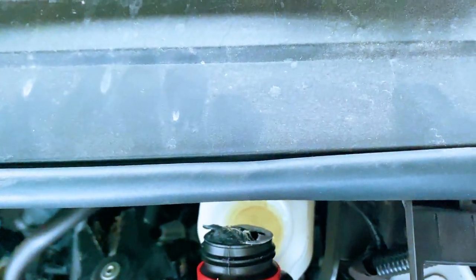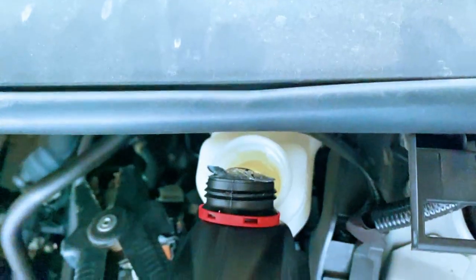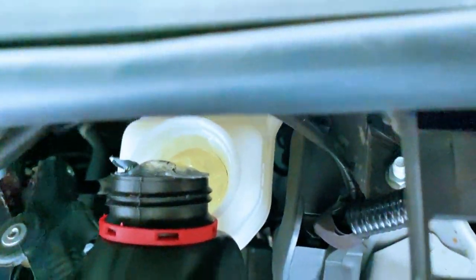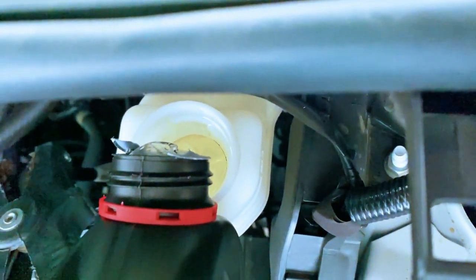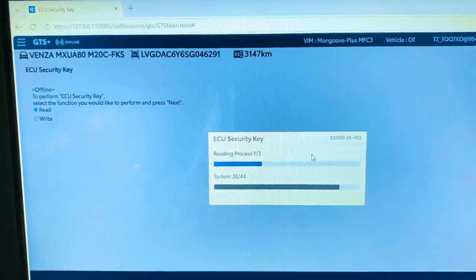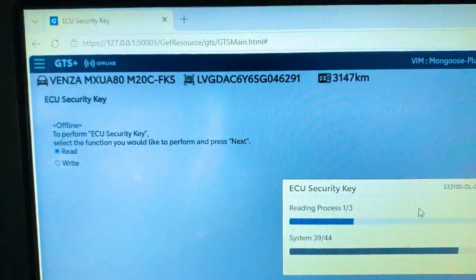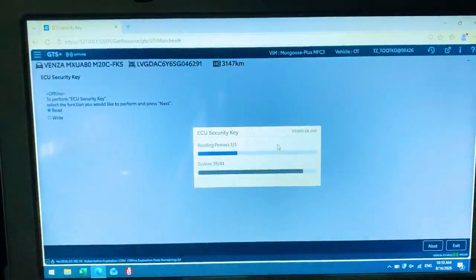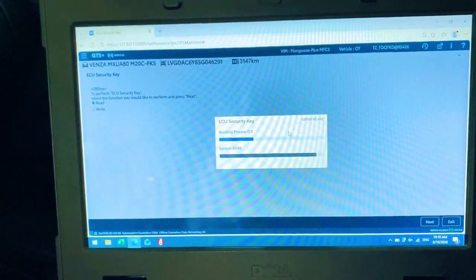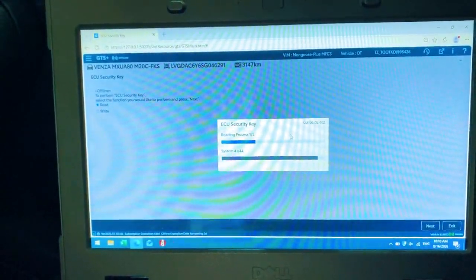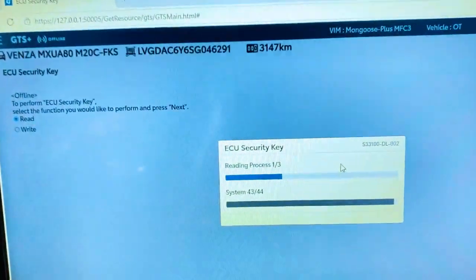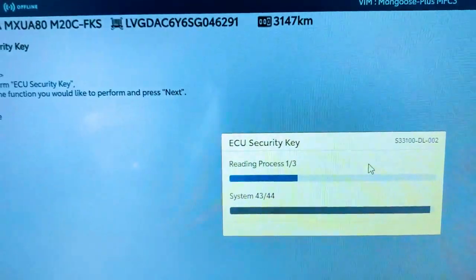The brake line connections also have specific torque specifications. Do not guess these values. Always use a calibrated torque wrench and the specification for the exact model and configuration. This is a hydraulic brake system, so correct torque is critical. Another important point from Toyota: do not remove the protective plugs from the replacement actuator ports before you are ready to connect the brake lines. And never carry or lift the actuator by its electrical connector.